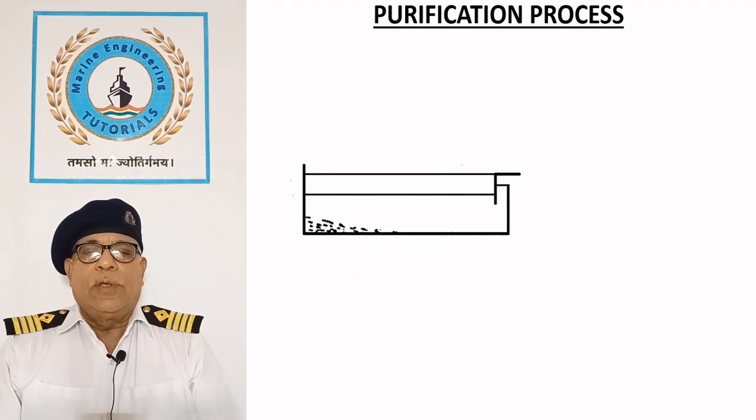Purification process. Purification is a process of separation of two liquids, usually oil and water. In addition, it can separate a small amount of solids. The sketch shows the conversion from gravity settling process to a purification process.